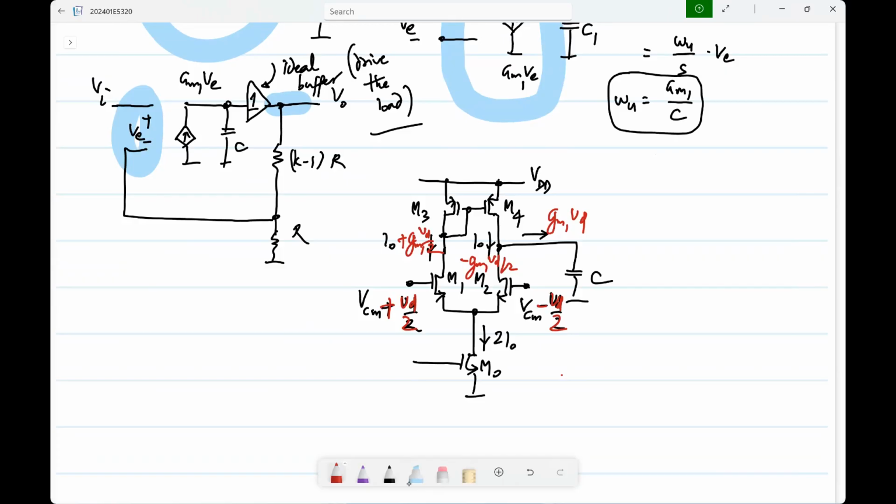So is this it? What difficulties do you foresee here, or what will go wrong if you mismatch? Okay. So whenever you make a current source, what is it that you would expect? What is an ideal current source, and what's the common non-ideal feature that you expect? Output resistance, right? An ideal current source should have infinite output resistance. A real current source, whether it is a controlled current source or an independent current source, will always have a finite output resistance. So what is the model of this differential pair?